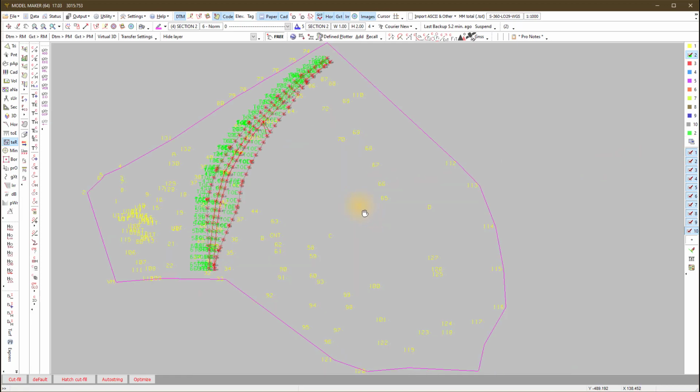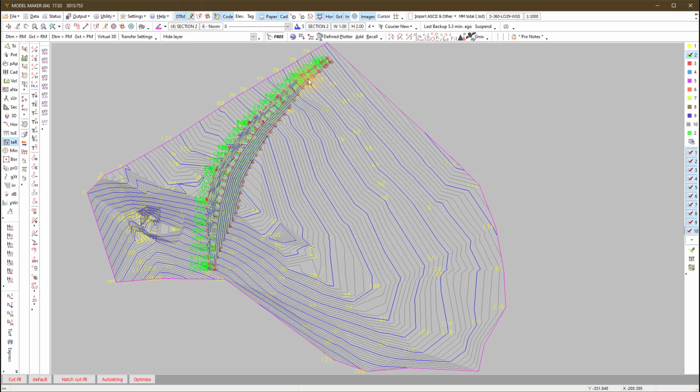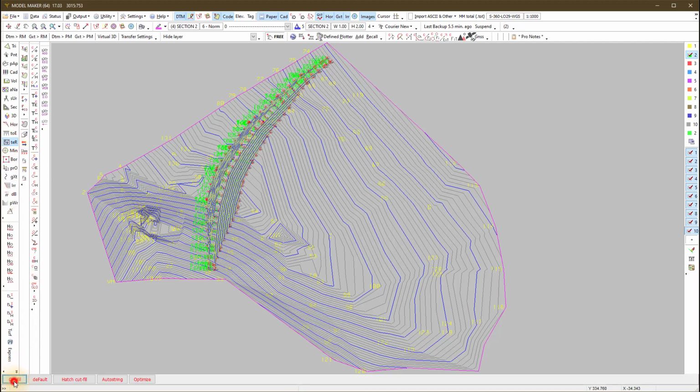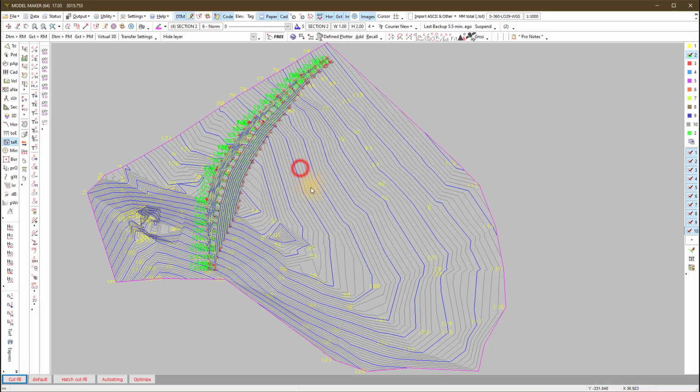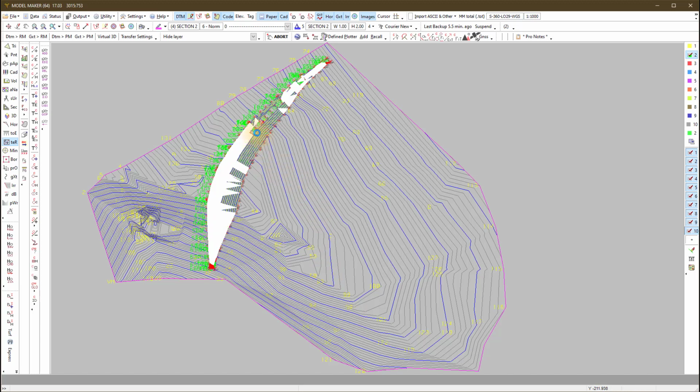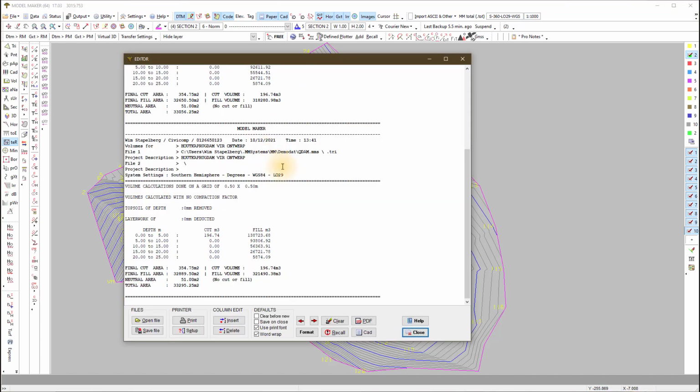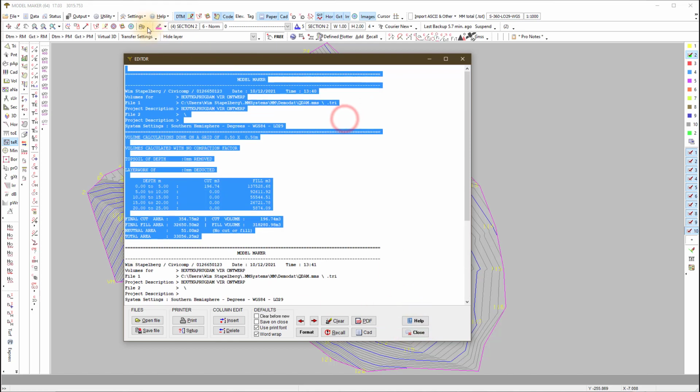And to calculate the water volume, I now need to determine where the water is going to be. It's going to be on this side. I merge the two projects, so I copy project 2 into project 1. Let me just quickly do the volume again, cut and fill, grid, and OK. Now it won't have that gap in there. So it's a little bit different, not that much. Then I just delete that previous one.